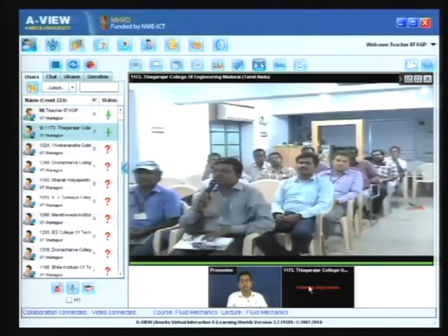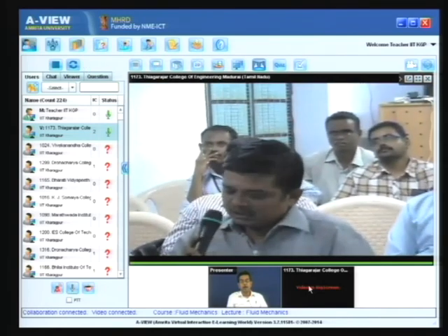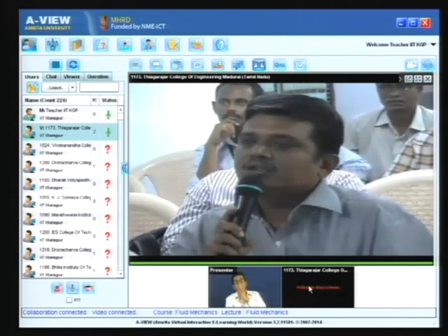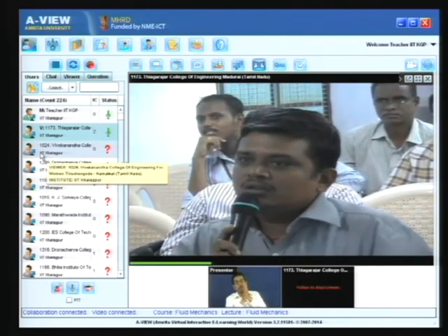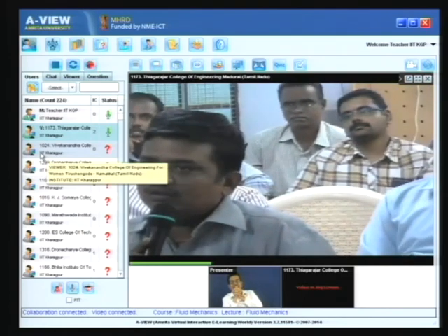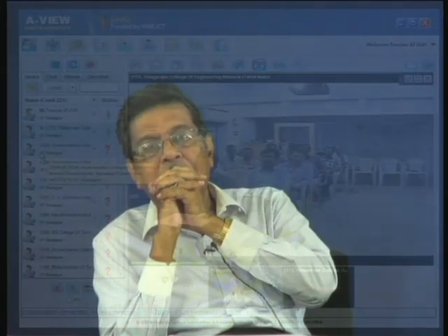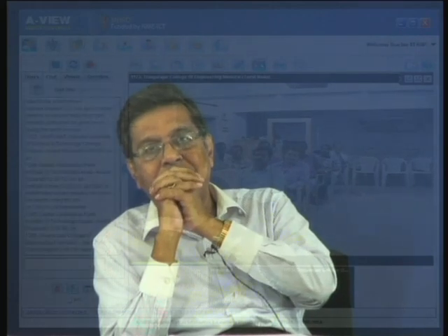Sir, I have a question from previous classes. Are there any other relations between boundary layer and friction coefficient, sir? Boundary layer and friction coefficient are very much related. You see the friction coefficient for a flow over a plate, flow over a surface, external flow, is defined in terms of shear stress divided by half rho v square, I told. The shear stress at the wall for an external flow is very much related with the boundary layer, because shear stress at the wall is determined by the velocity gradient at the wall.